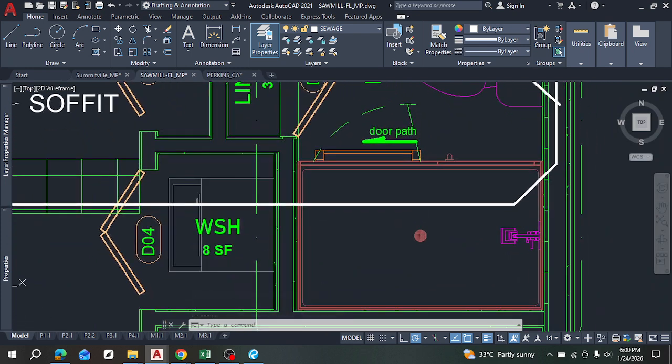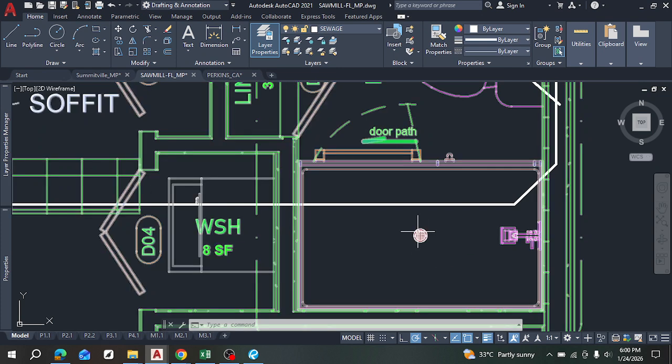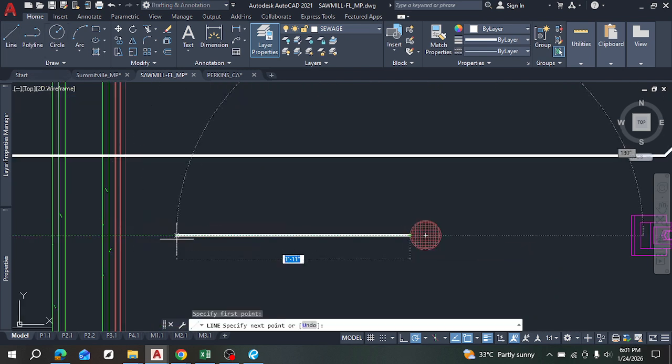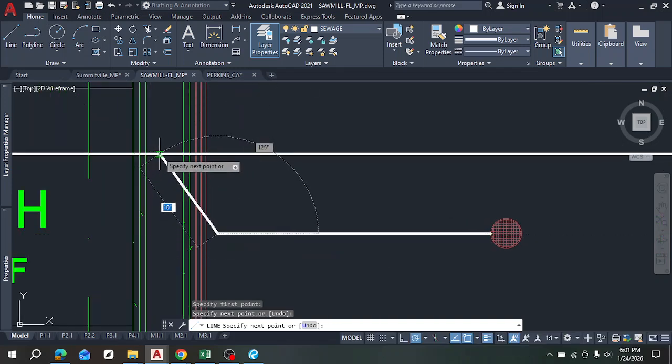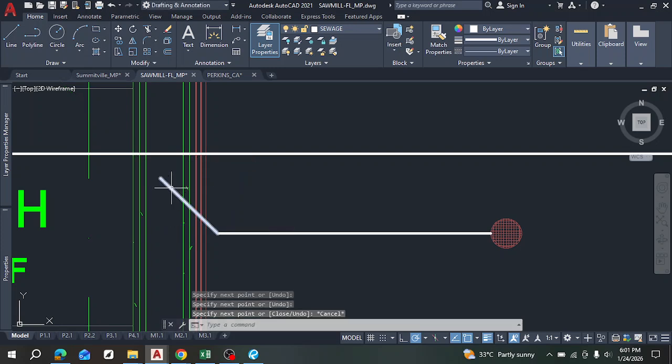Then this. Now I would have wanted this to enter into this wall behind, but it's just going to be very messy to connect into this. So I'll take it to the front instead. Luckily, this is on the floor, so it's just going to drop into the floor and then out into this wall. Why I need to go to a wall is because that's where we're going to do the venting, right? So it goes straight into this wall somewhere here, and then that 45 degrees, very, very necessary.